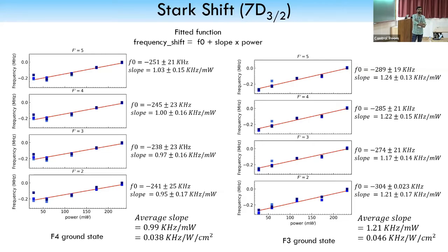When you average, it all boils down to signal to noise ratio. You can have a very broad laser, but you can still measure the center peak position. If you have a signal to noise ratio of 1000, you can split the line into 1000. So the line width will not come into the picture. In fact, if you repeat the measurement on the scope, you will not see that it is refreshing. It's so stable that if it was 100 kilohertz, you would see it jittering. Here, you will not even know that it has refreshed because the scan is completely phase stable. It's true anyway.